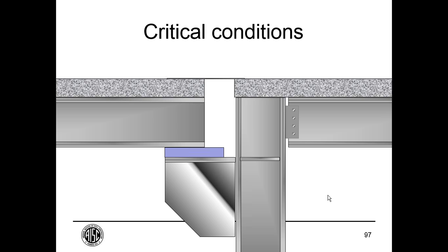You see the plate spanning over the seismic joint. We're making the estimate that the maximum displacement of each of these, instead of using just the design story drift, we're multiplying by 1.5. That's a correction of that 2/3 factor we saw early on in the seminar. And we're also correcting by the ratio of R over C sub D. So instead of amplifying our displacements by C sub D, we're effectively amplifying our displacements by the R factor. And then we're going to take the absolute sum.